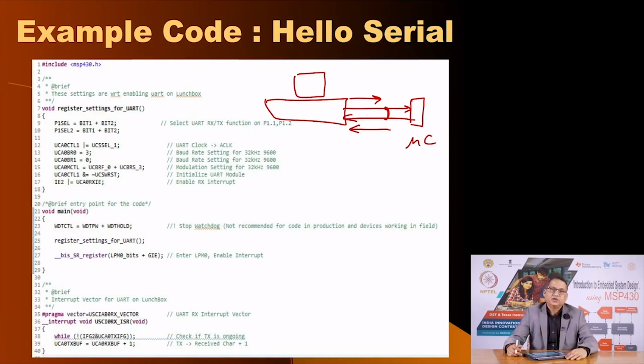And if you transmit information using the ASCII protocol, you know that the code for A, if you add 1 to it, you get the ASCII code for B. If you send 1, you will get 2 and so on. So, this is a very good test. Visually you can decipher whether the values that you are transmitting are being received properly or not. Let us go through that.